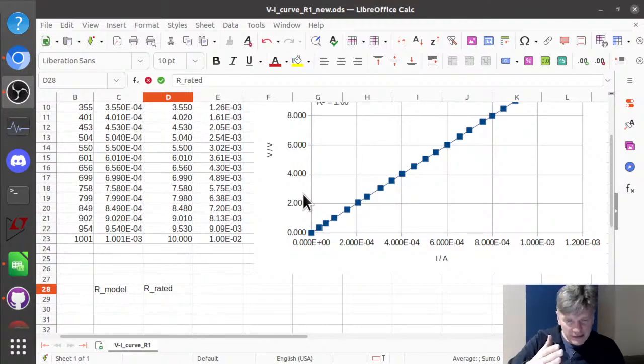And they have deviations because of the production. They are never ever precise. Usually they have errors around 2%, 5% or so. You can have very precise resistors as well, but usually it's not necessary. They can have these small deviations, but you see that here the error is even less than 2%. Maybe that resistor I used is rated to an error of 2%. We can calculate this later.